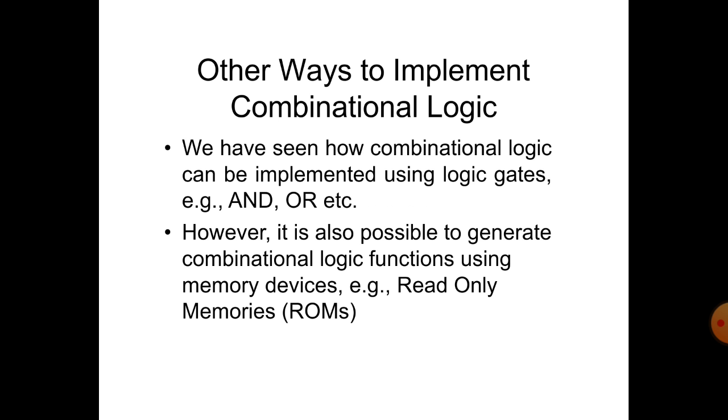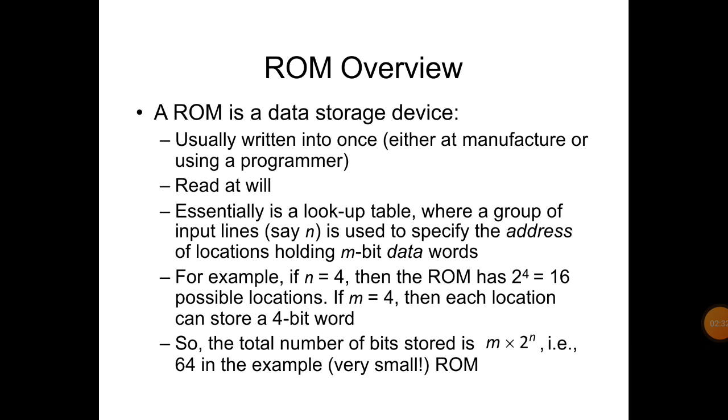Other ways to implement combinational logic. So we have seen how combinational logic can be implemented using logic gates, for example AND, OR, etc. However, it is also possible to generate combinational logic functions using a memory device, using read-only memories. And ROM overview. So what is meant by ROM? Read-only memory. It is a data storage device. Usually it can only read the data, but we cannot store the data. It is usually written once, either at the manufacturer or using a programmer.